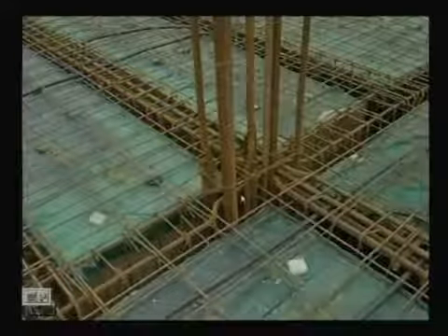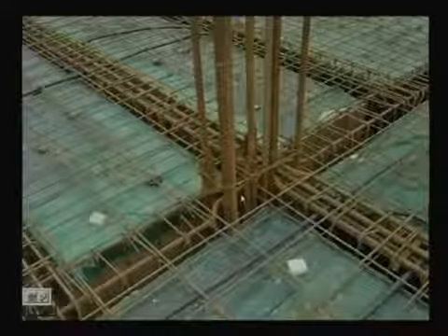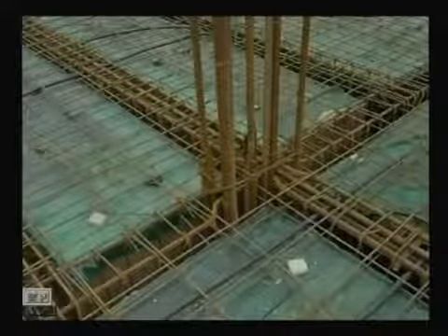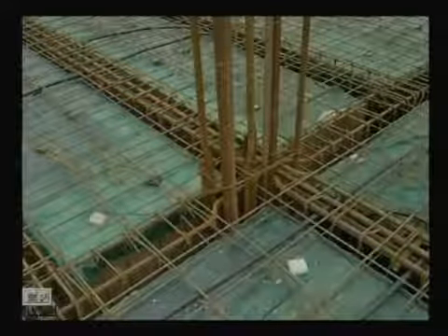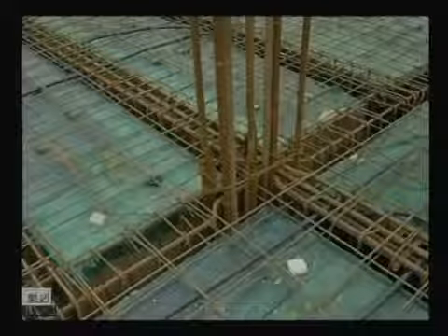So that's why it is very, very important that you check whether you have sufficient gap and how much the gap will be. If you consider the maximum size of the aggregate as 20 millimeter, then at least you have to provide 20 millimeter so that one coarse aggregate can be accommodated within that place. Our code says this in detail, that we shall come to afterwards when we come to detailing.